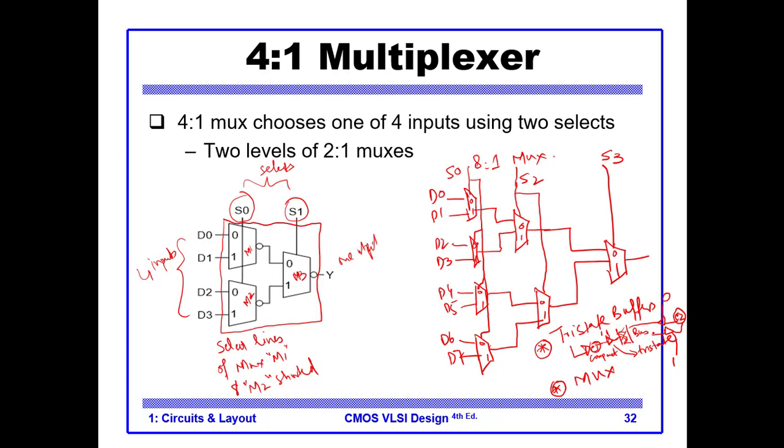So C2 will enable the receiving buffer. So this is the receiving tri-state, and this is the transmitting tri-state of C1. So C1 will also have a receiving tri-state. So all these tri-state buffers are controlled, and who controls it? The control unit controls it. And so that is the story of tri-state buffers.